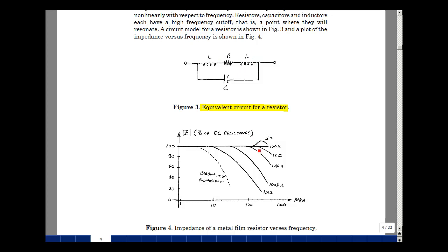You can see here for low values of resistance, we're getting a resonant peak, that the impedance of these two leads is large enough compared to R that we basically have a parallel LC circuit. So we're going to be measuring some of these frequencies in lab.